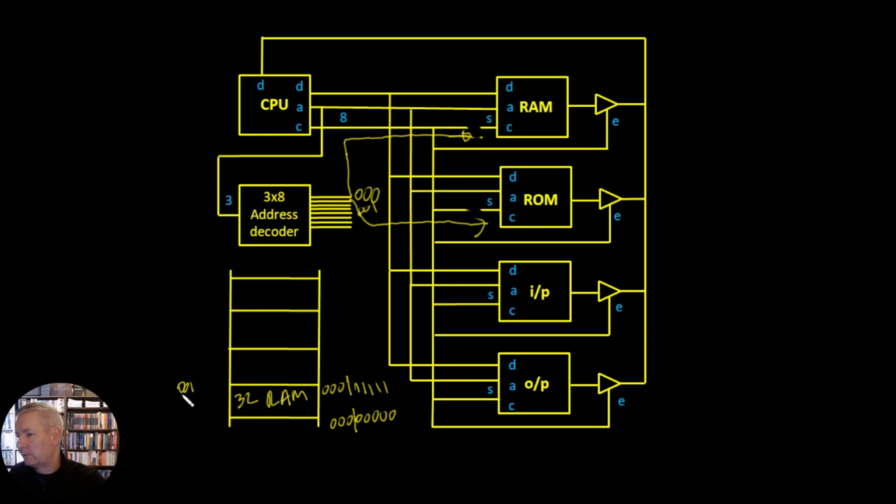And we talk to this device between 0, 0, 1 and all zeros, 1, 2, 3, 4, 5, and also 0, 0, 1 and then all ones, 1, 2, 3, 4, 5. So if we're in between these two memory spaces, then we're talking to the ROM. And we can do that continually for each of the 8 devices. So that's how our memory mapped I/O works.